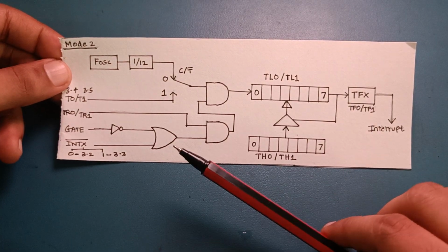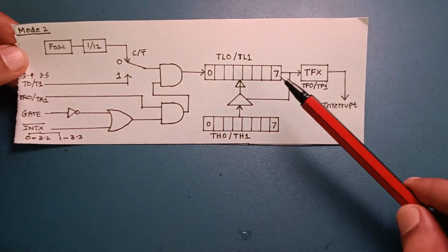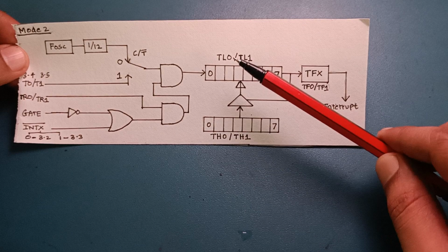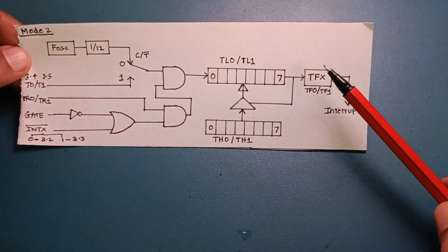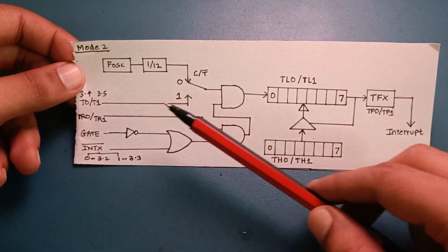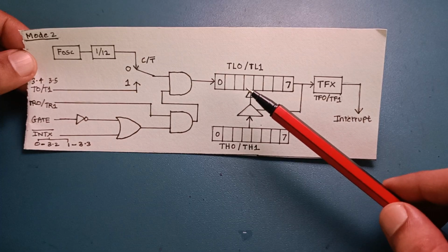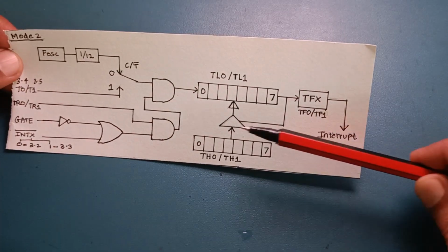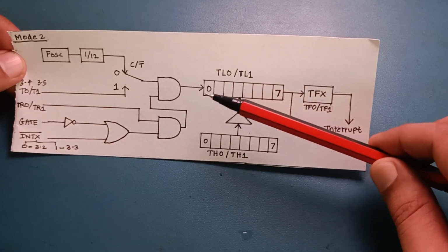So this is a logic diagram of timer 0 in mode 2. In mode 2 it acts as an 8-bit auto reload. So every time the 8-bit timer TL0 overflows, it will reload the value from TH0 into TL0. The counting will start from that count. So this part remains the same, right? Gate is 0. When you start the timer, it will count the external pulses, the falling edges. And when the count goes from FF to 00, it will trigger a buffer which will load the values and set the flag.